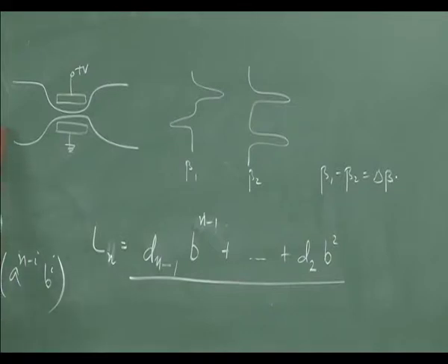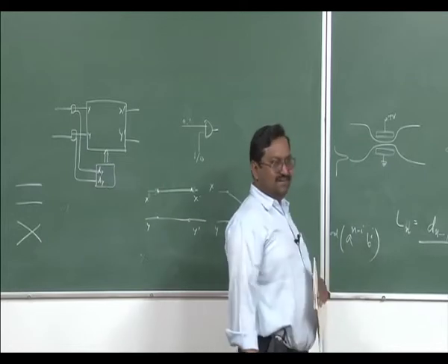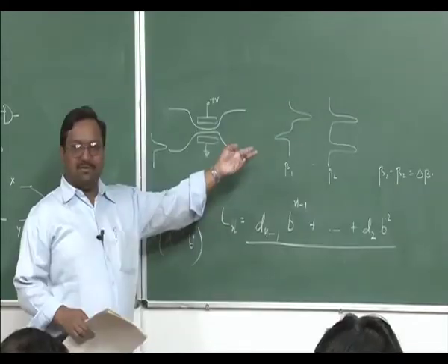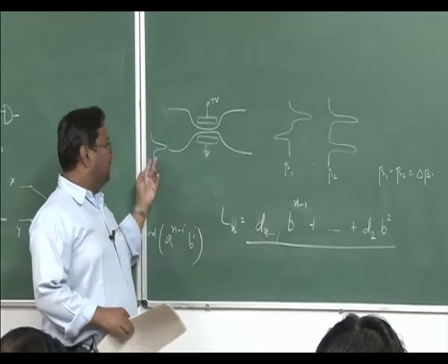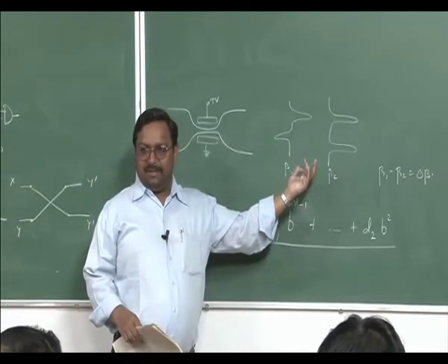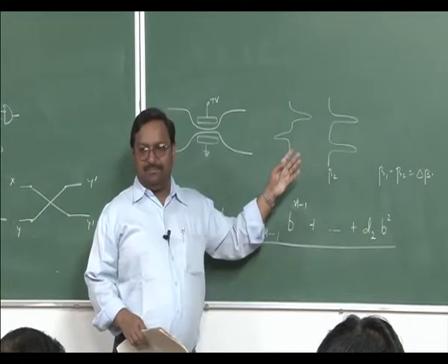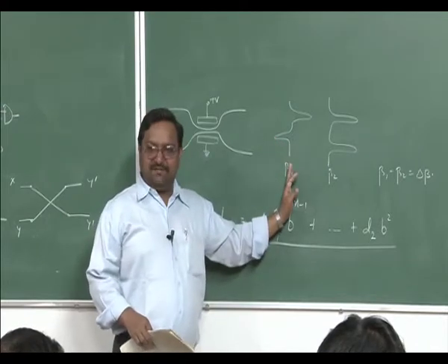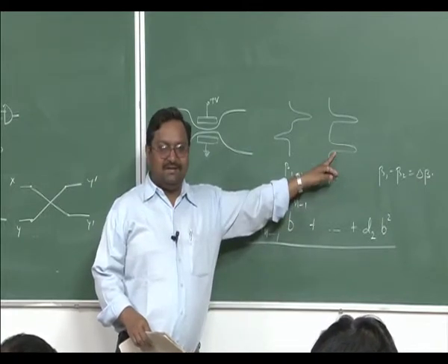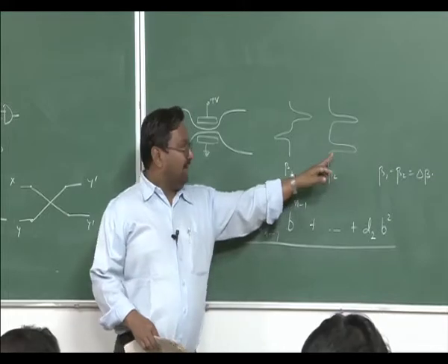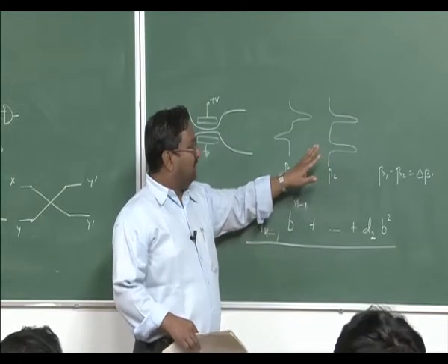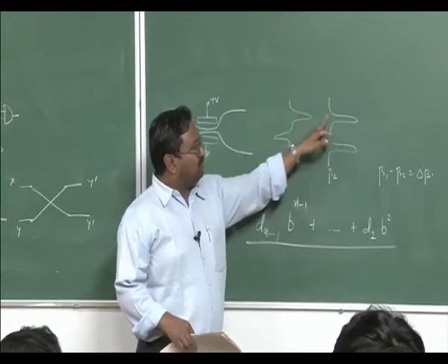Usually when you put a profile here, it will excite, though this is not a mode of the system; these are the only two modes. So this has to be represented uniquely by a linear combination of these two modes. If both are of equal strength and you add them, with a 180 degree phase shift on one, these two become the in-phase component, and the out-of-phase ones cancel each other.